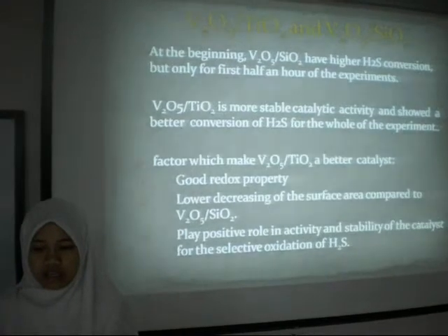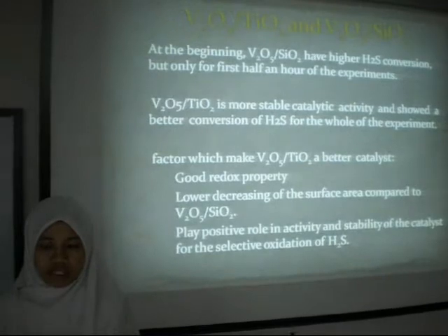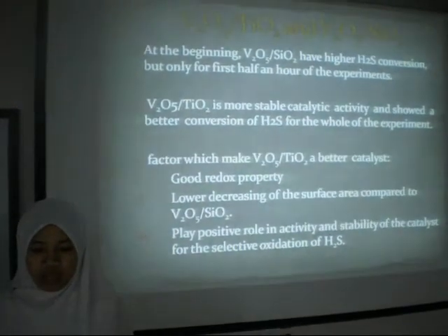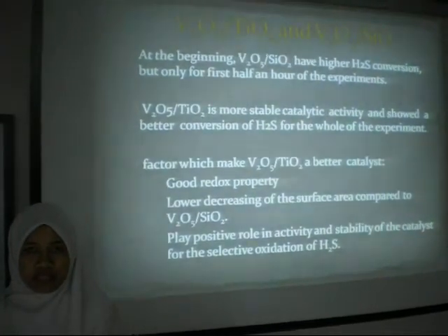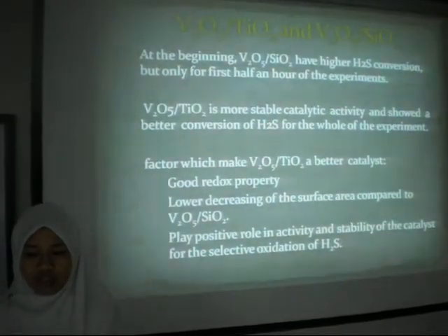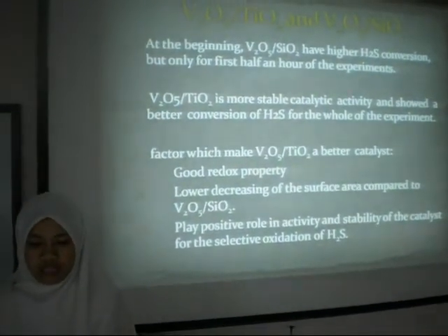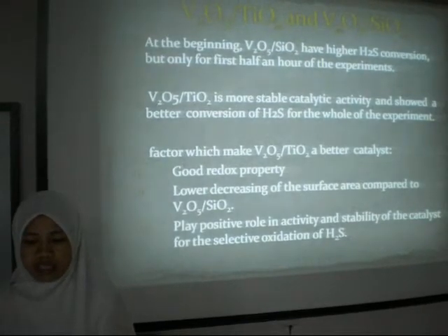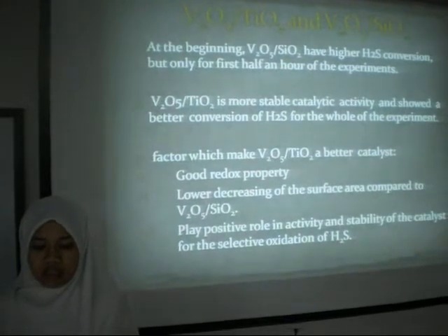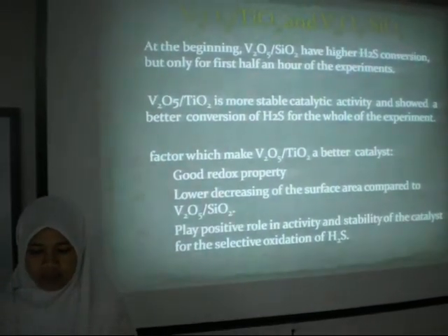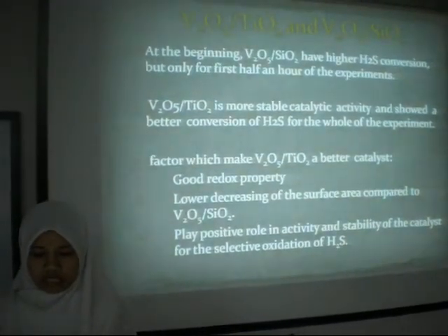At the beginning, silica vanadium hydroxide has higher conversion of H2S, but it's only for the first half an hour of the experiment. Actually, titanium vanadium hydroxide is a more stable catalyst and shows a better conversion of H2S for the whole of the experiment. The factor which makes this catalyst better is that it has good redox properties and a lower decrease of the surface area.